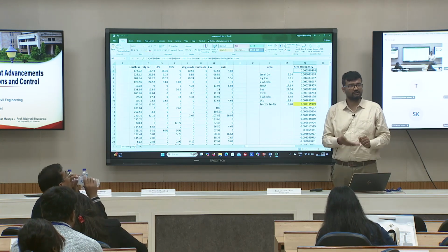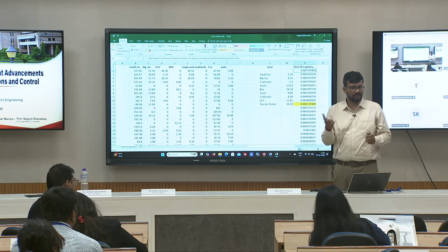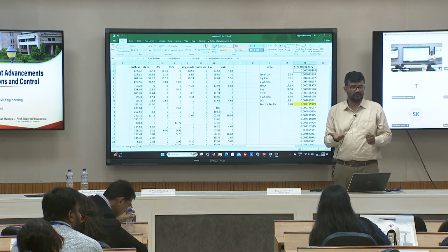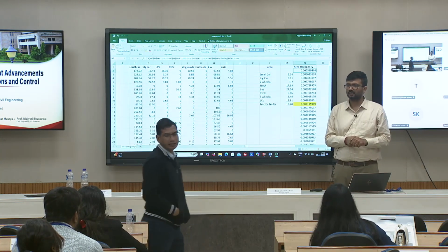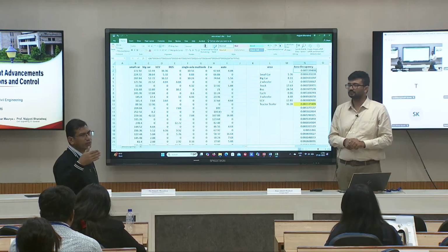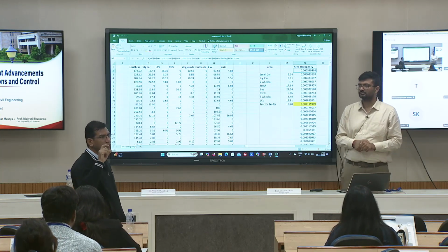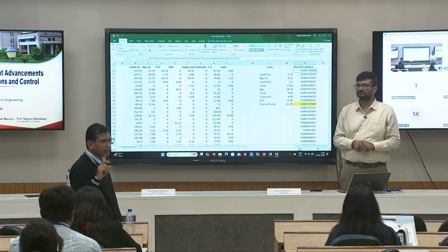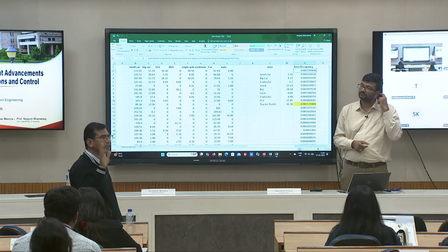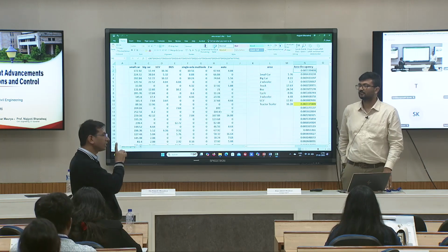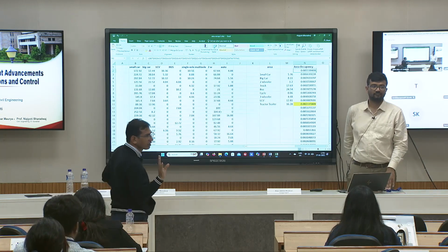So you can develop occupancy related plots also, instead of density. In density, one of the problems is that you need to define it in PCU, and PCU is a big issue. There are too many theories on adopting PCU. So this is one approach where the PCU concept is not required.